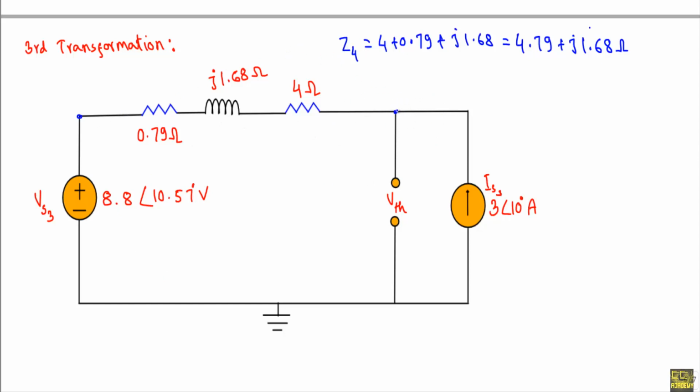Now see, in this circuit, let's say this is our node 1. In this node 1 we have node voltage V1. V1 is exactly equal to the Thevenin voltage of this network, and this will be our reference node. This reference node will have a voltage of V0 equal to 0 volt. I will apply Kirchhoff's current law at node 1, or I will use nodal analysis in node 1. See, the current is entering from this direction in node 1. As we do not know the current flowing through the impedance Z4, the current will be outgoing in this direction from this node 1.